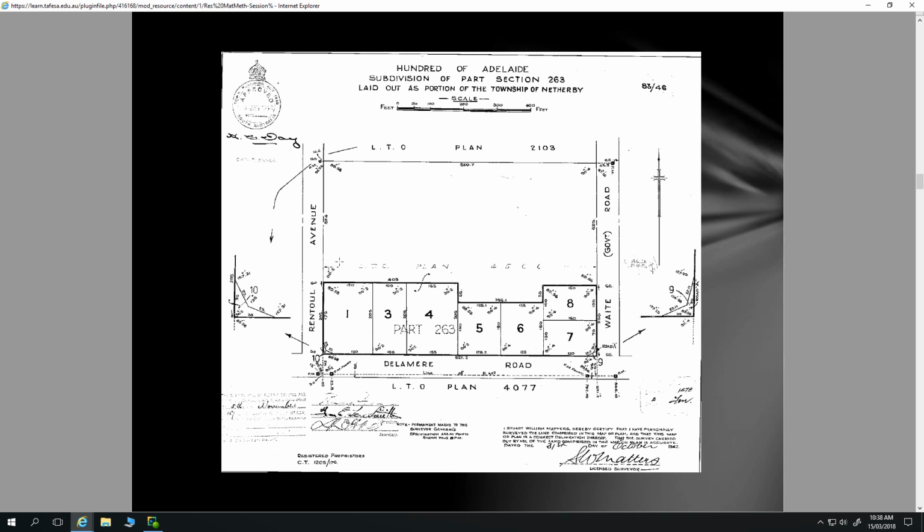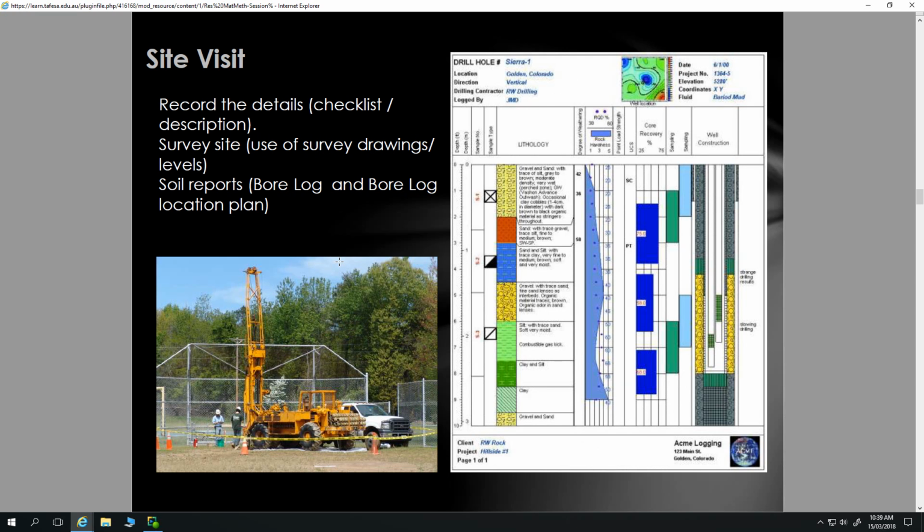And when you're dealing with old titles, some of the survey plan images have all been redone into metres and millimetres, or possibly everything's been redone now. But it wasn't all that long ago when I was working with older titles that I was doing a lot of conversion from feet, inches, roods, perches, yards, etcetera into the metres.